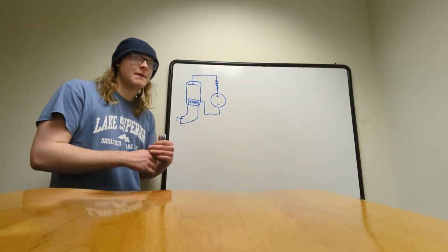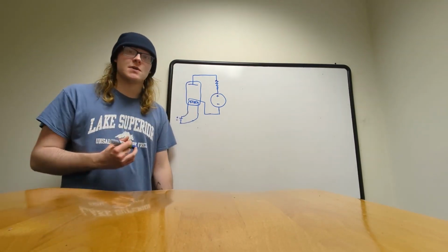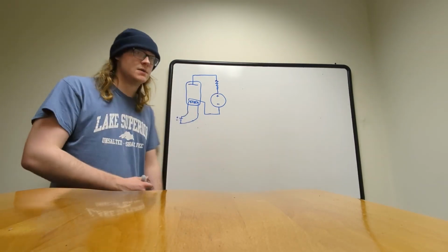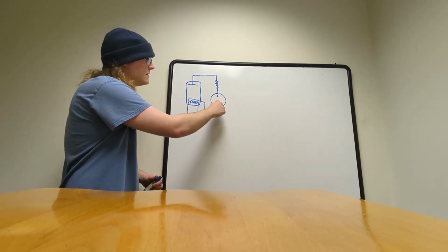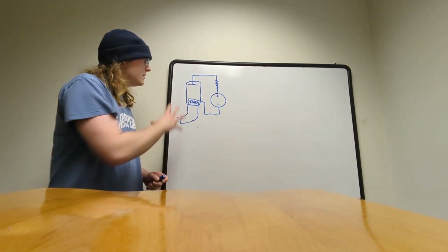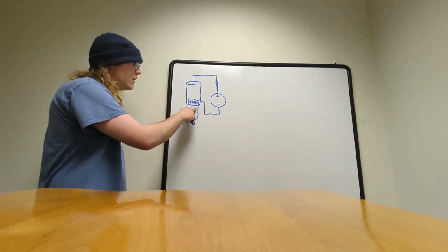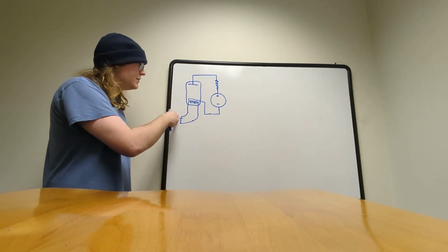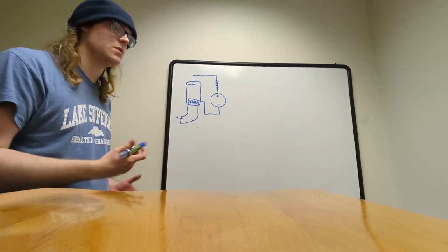All right. Now that we have the basics of how these vacuum tubes operate, we can apply them to circuitry and see how they behave with exterior voltages, loads, and other circuit components. Now consider the following simplified circuit. We have a positive to negative voltage source across some resistor load, and we have our diode, a vacuum tube, in this circuit. It's worth noting that the filament has a different voltage supply across it than the voltage source going into the main circuit components, which will apply to our diode.